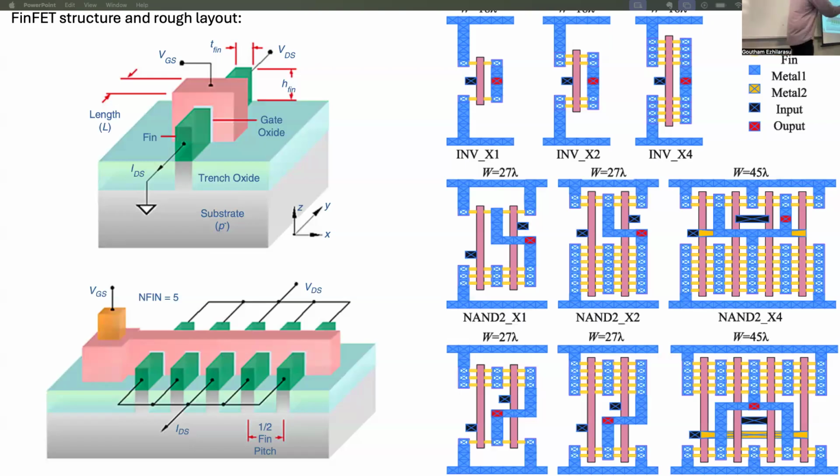And so you can have very complicated layouts, but obviously we're not going into it, depending on what your gate topology is. When you build a chip, you have a whole bunch of these on the chip. But again, no one does this by hand. There's usually software that automatically generates all this. But in our case, we're particularly talking about this, okay? So even your layout for this particular process is going to look something approximately like this. There will be other masks also for the implant and all that, which I will talk about next.